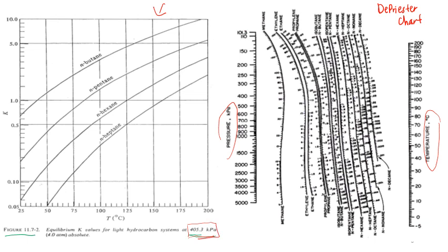but if you don't have something like that, you have to read the pressure, let's say 405, so 400, about maybe here, and then the temperature at which you want to read the K values. I'm just trying to show you how to read the chart. So at this pressure, let's say you want to read at a temperature of 90 degrees Celsius. You have to connect 2 lines between this pressure and this temperature, and then you find the K value for the component that you want.